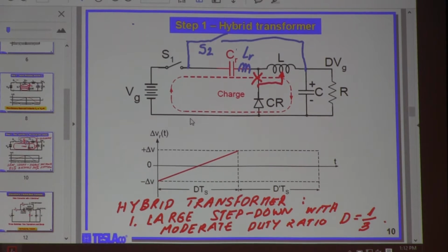But what I gain is that now, also, you see in this loop, when this capacitor is here, I always marvel how Intel would buy for $10 these VRM converters based on a buck converter, and they have a $1,000 processor. And then what happens if the main switch on a buck converter shorts? Tell me. If the main switch shorts, you're going to get all these 12 volts on the output, and you're going to fry the $1,000 microprocessor.